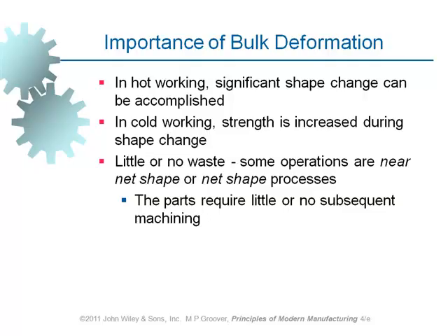That's something that we had in Materials and Manufacturing 1. What temperature is called recrystallization temperature? A temperature at which new grains of the material are formed. New grains are nucleated and they grow at that elevated temperature. Meaning, why is it called recrystallization? Because new grains are nucleated and they grow, which is called recrystallization process.